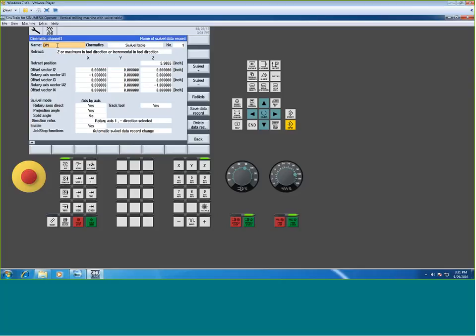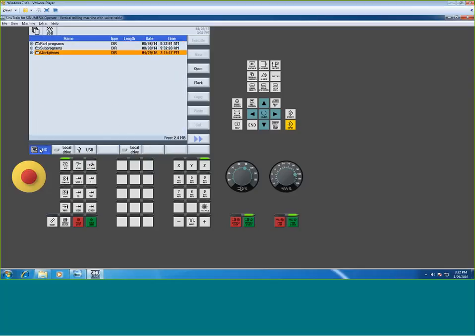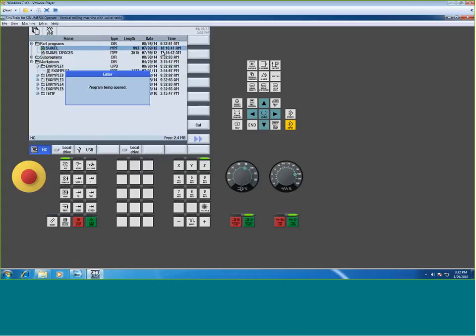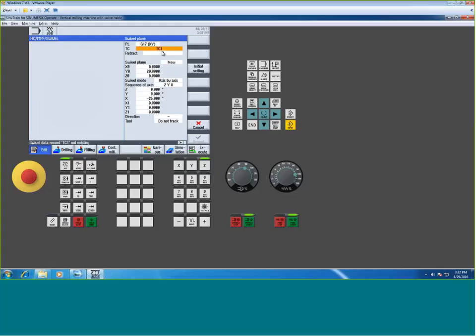Well, nobody says that you can't go in and change the name. You don't have to do anything else but change the name. Now, whether I'm using an existing program, I don't know if I have anything in this machine here. No. Oh, yeah. So here, now when we go into the cycle, you'll notice DMG comes in the list. And actually, TC1, once I save this and we reopen it, TC1 won't even show up anymore.